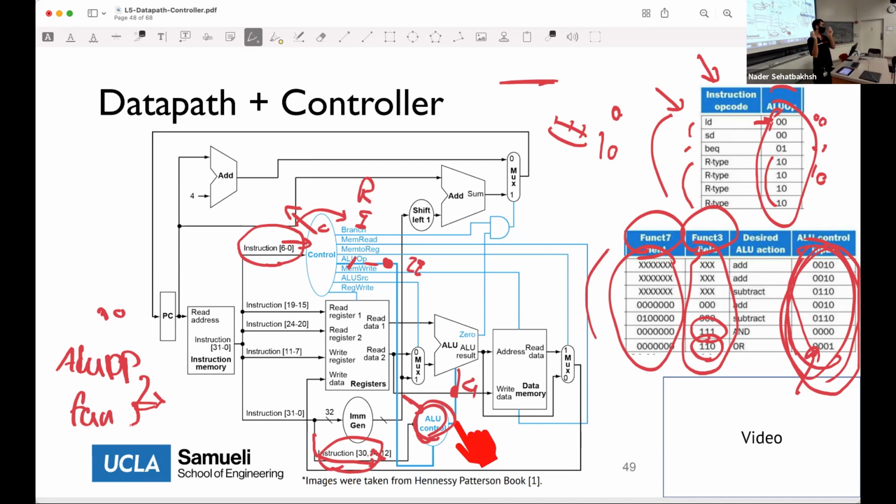Now that we have the same opcode for different R-type instructions, we want to avoid the scenario where, in order to understand which R-type instruction this is, the controller has to take multiple steps. For example, in the controller, we could easily go through func3 and func7 until we figure out which instruction this is. But the problem with that is that it takes more time for some instructions and less time for others. And that's what we don't want.